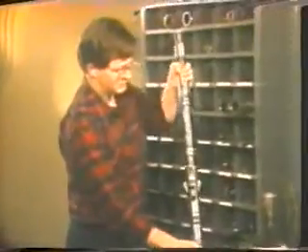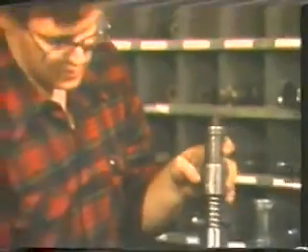Upward jarring then shears the pins between the running tool and lock assembly, which releases the running tool from the lock and allows retrieval of the wireline tools. The equalizing subs that are used with Otis and Camco equipment can also be adapted for use with Baker equipment.